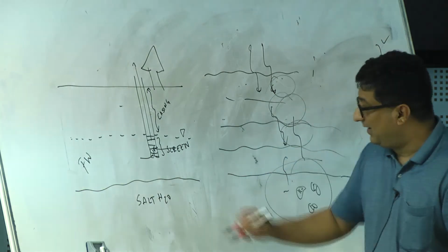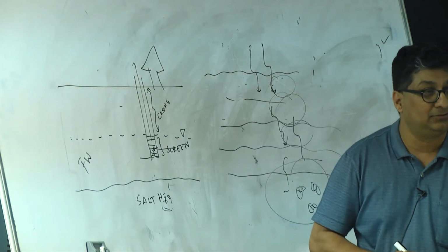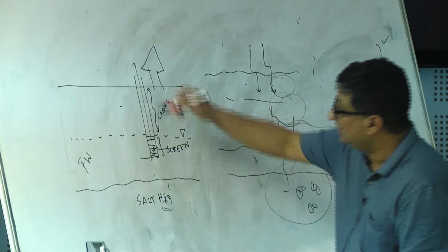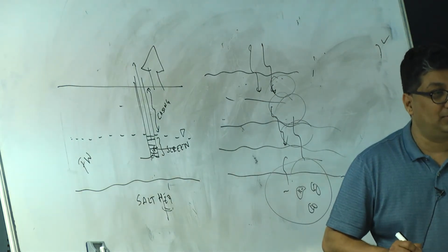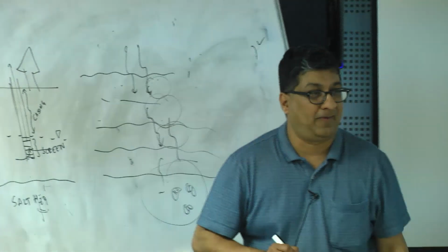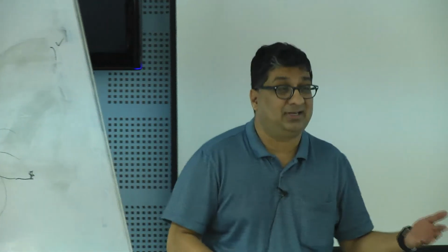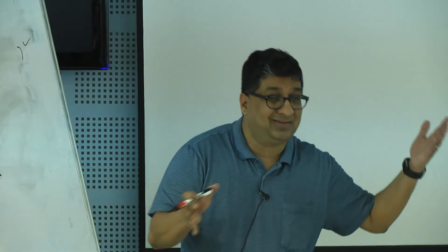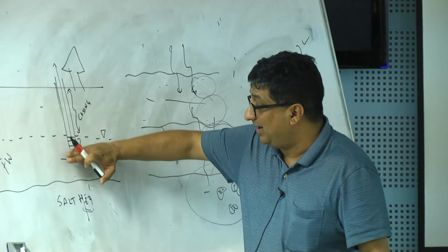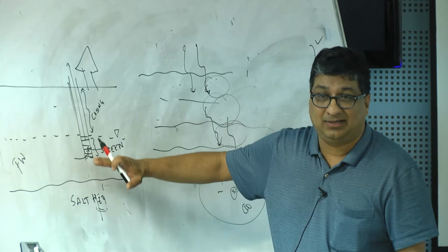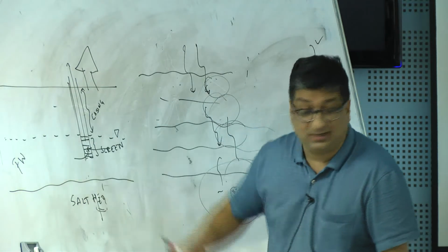If I put this screen somewhere in the saltwater zone, obviously I'll pick up salt water, right? So I don't want to do that. So before I put the well, I actually drill a hole and run some geophysical logs, and what that geophysical log tells us is how much salt content there is. It will tell me where the water is, and how much salt content there is. It gives me an estimate. It's not a true value, but it can tell me roughly how much salt is there. And if I see that it's too salty, I don't want to put a well. I'll go back and fill up that hole with cement or bentonite, and then I'm going to put my well here. So I have salt water here, fresh water here.